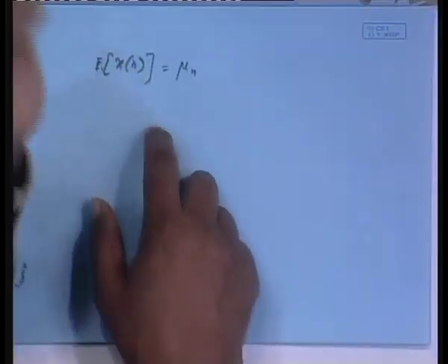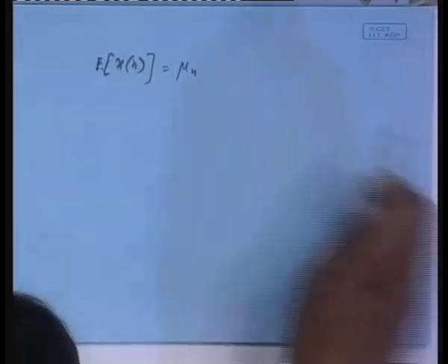If it is purely random, it does not know where its origin is, it does not care for this time axis, this randomness is going on homogeneously from minus infinity. Then whether we measure the mean at the nth point or mth point or kth point, you should ultimately get the same thing. You can model that way, and this is only an ideal model, by the way. So, then it is called a first order stationary process. First order because only x n, no product, no square term or product term.